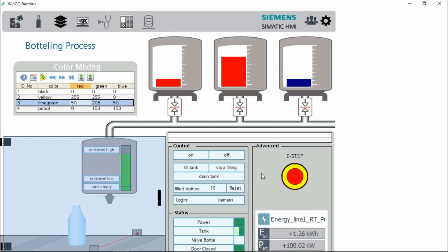That's it. That's all I wanted to do. After your runtime, just going to restart the graphics runtime. Switch to my volume screen. And I see now, of course I didn't do it for the two others now, but in the first I/O field, I actually see the content of my tank here. Okay? So that's what's the fill level right now, of the tank.